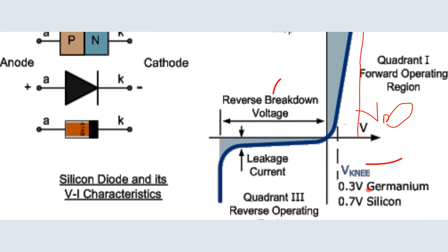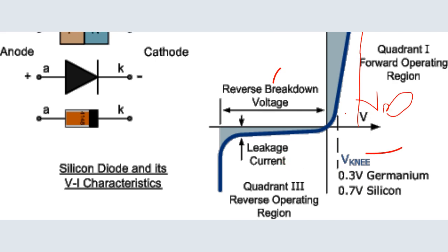The knee voltage, because it is a result of the internal properties of germanium or silicon materials, is estimated at 0.3 V and 0.7 V. This helps industry manufacturers determine how much external voltage we need to overcome the knee voltage. Then from there, we don't need so much voltage to operate. On the other hand, if we operate in the reverse direction,